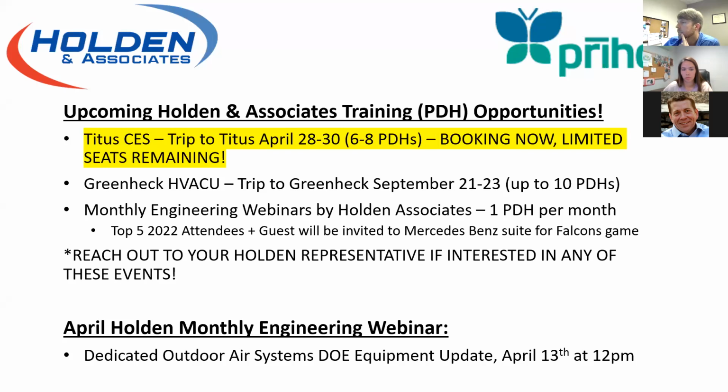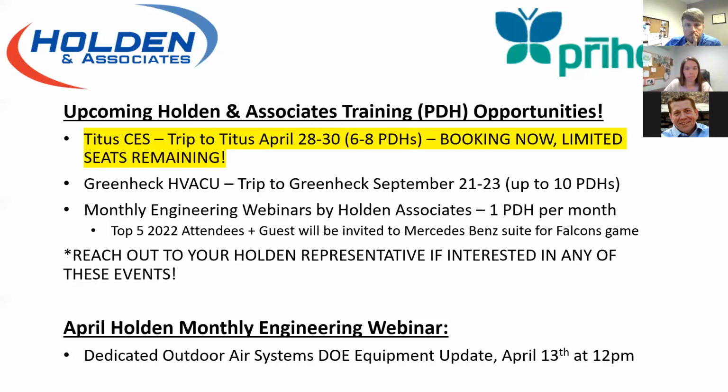We can do insulated versions of all of our diffusers. Depending on specifically what's being transferred, we probably need to look at it in a little more detail, but transferring supply through an unserved space, yes, we could definitely provide insulated fabric for that. That would help to eliminate any problems with condensation depending on the temperature differentials. So it is possible. We don't do a lot of insulated systems, but it is definitely something that's pretty easily capable.